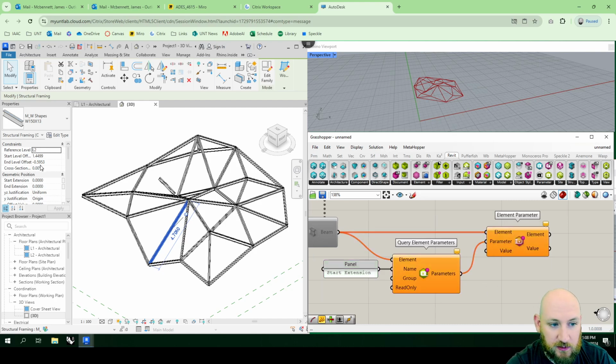And then what value do I want it to be? So the same as I can select this and go to 0. I could change this and make this whatever number I would enter in Revit, I can enter here. So minus 0.25, but I want it negative, so it shrinks it and doesn't expand it. And that is the value.